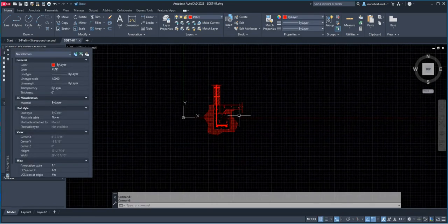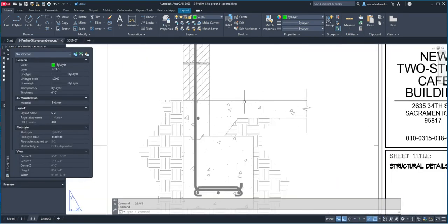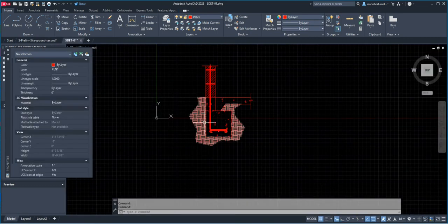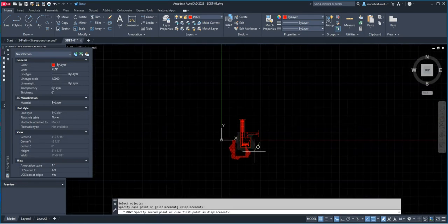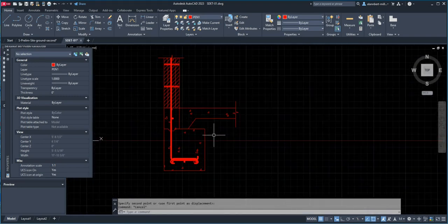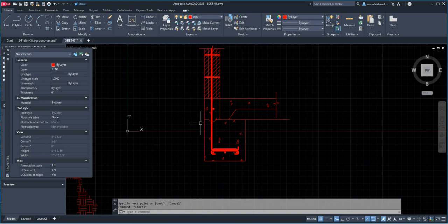And if you wanted to change your detail, so for example, the underside of the slab actually has some rocks, which we call an aggregate base, and it doesn't show here. So if you wanted to modify this, you need to open up the detail where you drew it, and let's put some aggregate base there. We're going to do a line here temporarily, and then do a P line from, say, here.